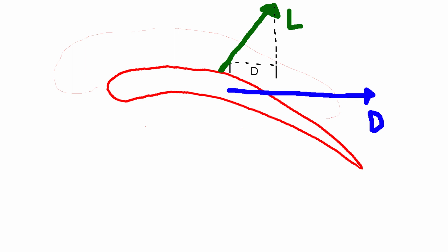Skin drag comes from the friction of the air scraping against the body of the plane as the plane moves forward. Form drag is the force coming from the object bumping against an adverse pressure gradient. Think of it as the drag from the front of the plane hitting against the air at speed. Induced drag is the component of the lift force aiming backwards compared to the plane's velocity. This is a necessary component while producing lift.